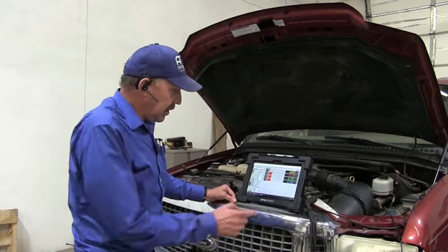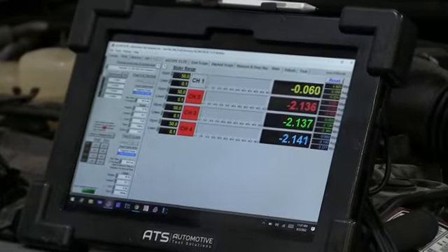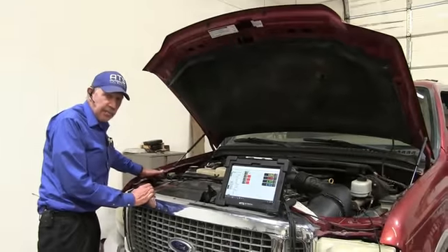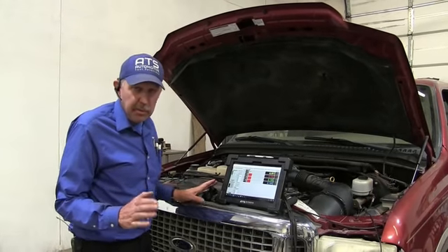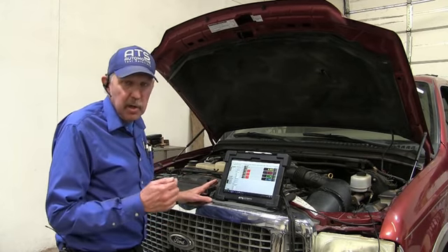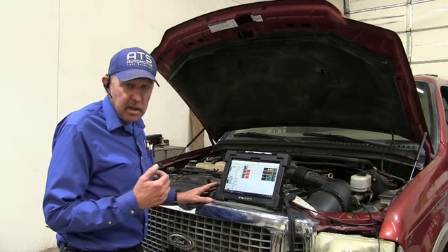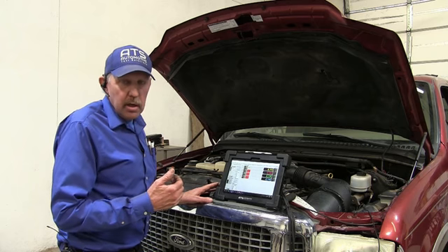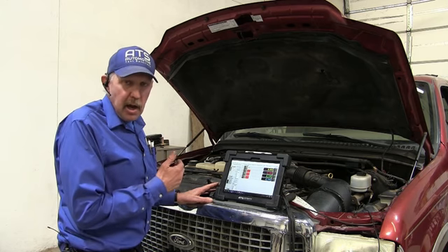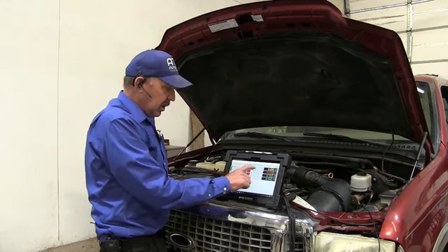Okay guys, so I'm in the wire and I'm in it. The red light's out. The other thing I didn't show you is the negative lead is on the battery. The only acceptable place when you first start to work on a car to have your scope lead is on the negative post of the battery, because I don't know if I've got any voltage drops yet until I've confirmed my grounds. Until I do that, I always get on the battery ground so I don't get burned. So I'm in the signal.